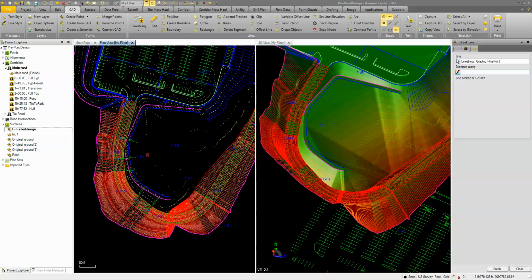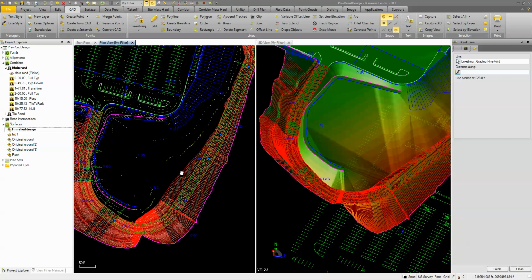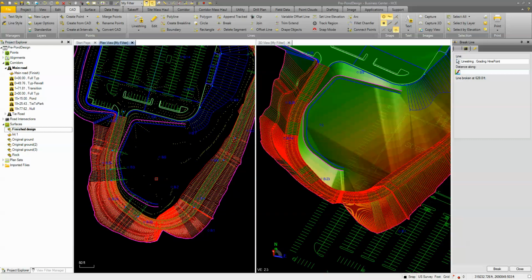We've got a 2-foot freeboard, and we're going to have a 0.5% slope catching the water from this area here and moving it down so that it drains down here, where we'll have an emergency spillway, and then also drain it out of the pond into this channel, where will be our discharge off our site. So we need to determine that, and I'm going to show you how to do that next.